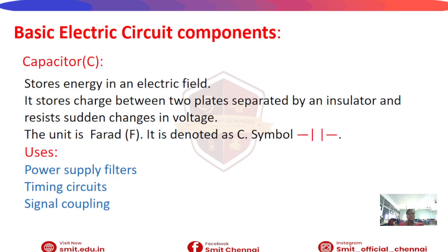Then capacitor. A capacitor stores energy in an electric field between the two plates separated by an insulator. It resists sudden changes in voltage. The unit of capacitor is farad. The applications of capacitor are used in power supply filters, timing circuits, and signal coupling.